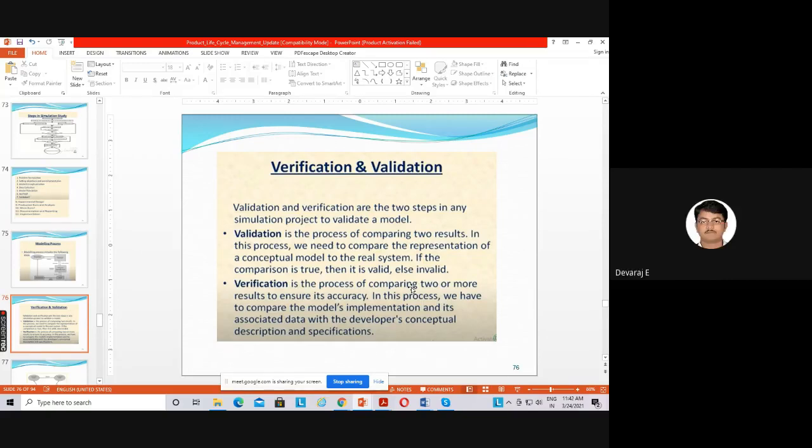Okay. So we should check two ways. One is the material and the manufacturing process. If you are using the casting method, there may be a lot of defects inside the material while manufacturing the product. So you should check that. And second is whether the design we made according to the numerical analysis is the same design we have manufactured practically.